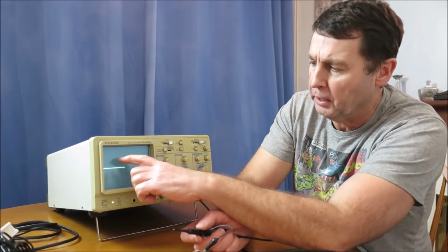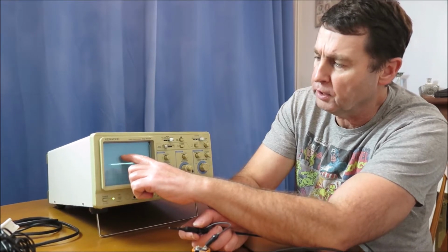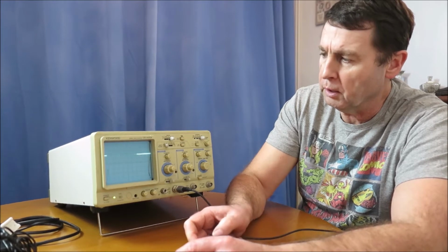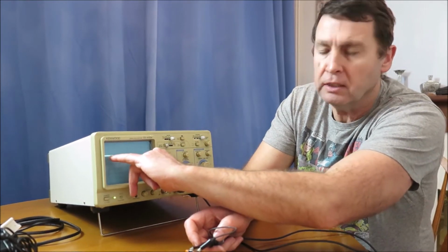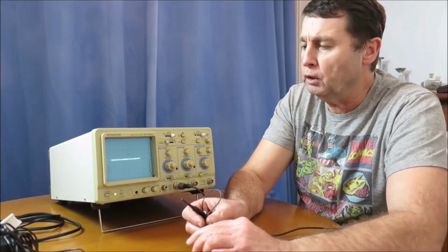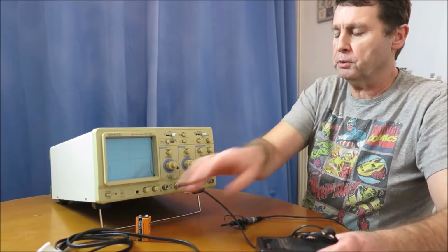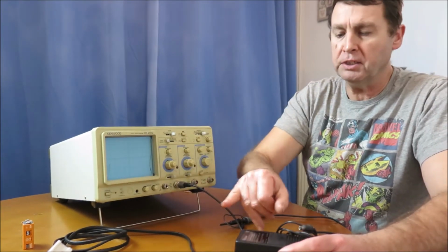This is a 9-volt battery. So I'm estimating it's going to come up just short of that square there. So let's have a look. And there we are. So that's 9 volts and it's DC. It's a straight line, a flat line. And that's what we're looking for from our power supply. So we want AC in and we want a flat line DC out.